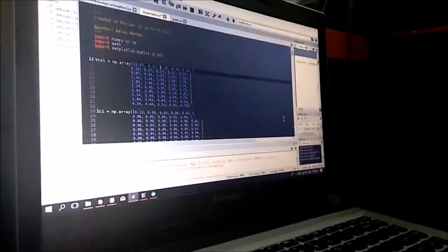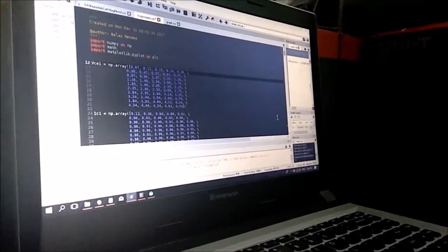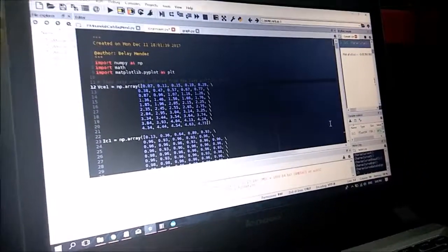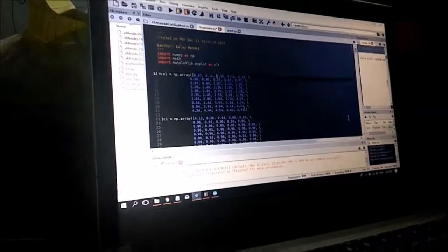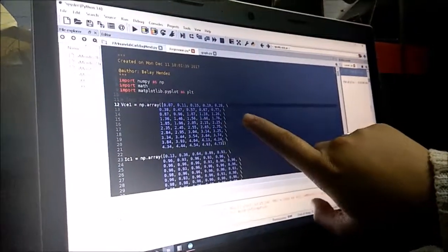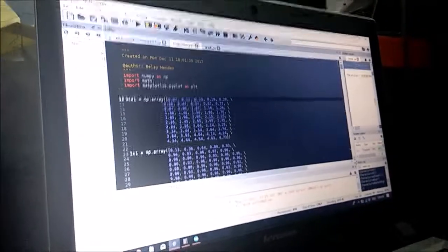The data we have obtained from the live plotting feature of Python from the Arduino curve tracer is transferred to the Spyder Python environment for us to check the series of points and plot it through matplotlib and using polyfit. We already got the equation for each characteristic curve using regression. I'll explain briefly the code for the Spyder Python. So we have loaded the data arrays gathered from the live plotting feature.